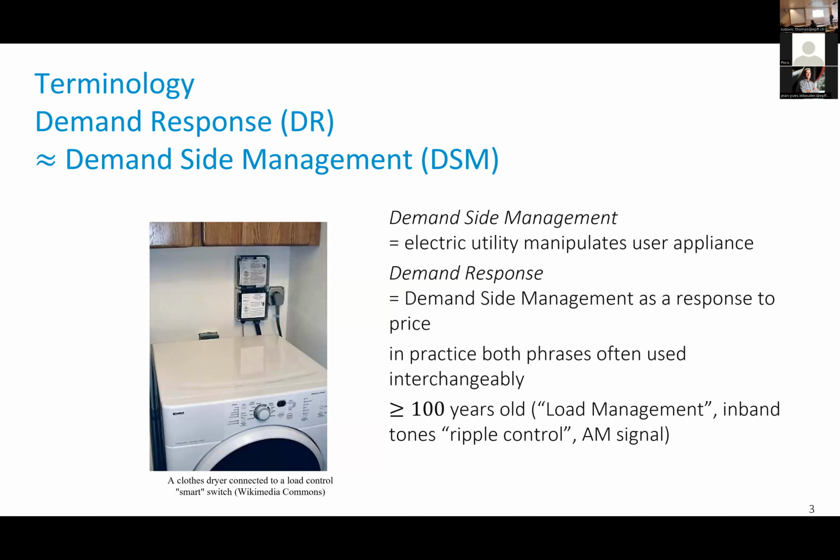The electrical line, in principle, is not a communication line, but you can send some very, very low bitrate signal. For example, you can send a tone, a signal that has a frequency of several hundreds of hertz, in addition to, with zero, a tone of reactive power. If you want, zero energy is transferred through that, but it serves as a signal by a system that captures the signal and says, okay, this boiler can now be switched on or off. So that's a way that many grids had to control when the night shift would start, for example, to make it more or less variable.